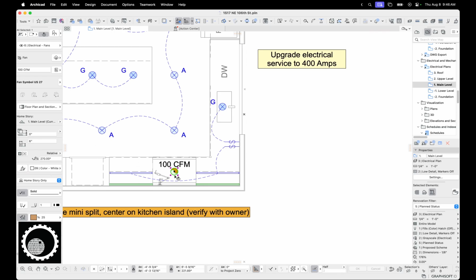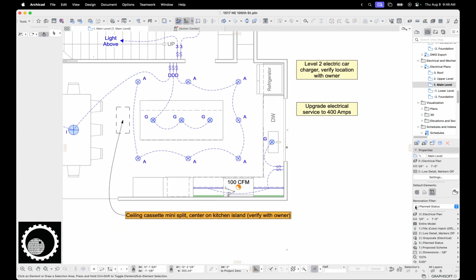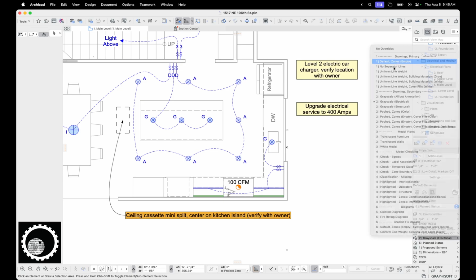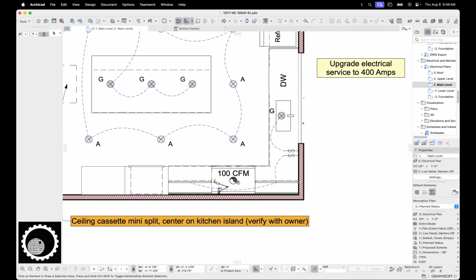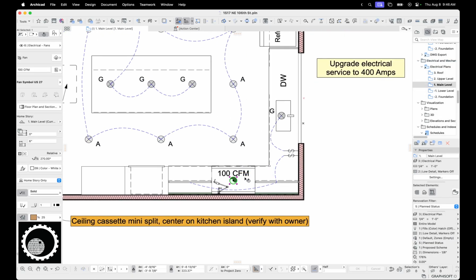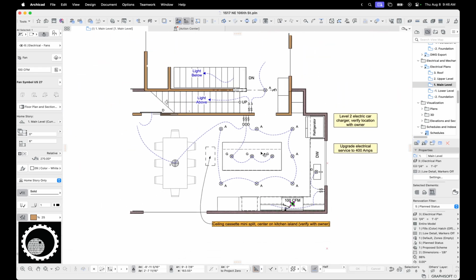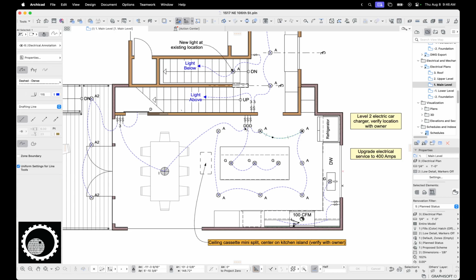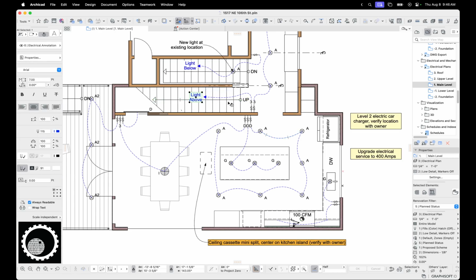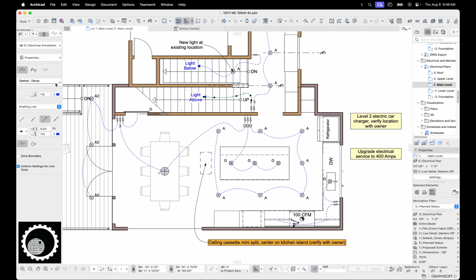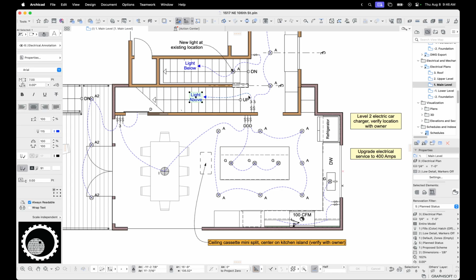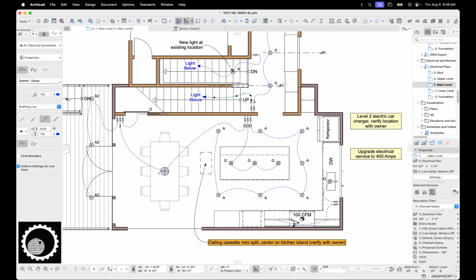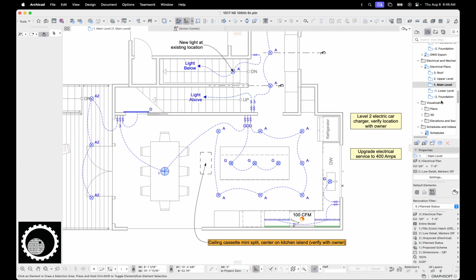Similar here, we've got the orange fan to make that pop, but if we go to default zones, that disappears, and it's no longer overridden. It just shows up with black because that's what I needed to show up. You can see here also as I switch between graphic overrides, these switching lines and this text stay blue because they're just regular text and splines that have their color set not by graphic overrides. Whereas if we go back, that and everything else switches.